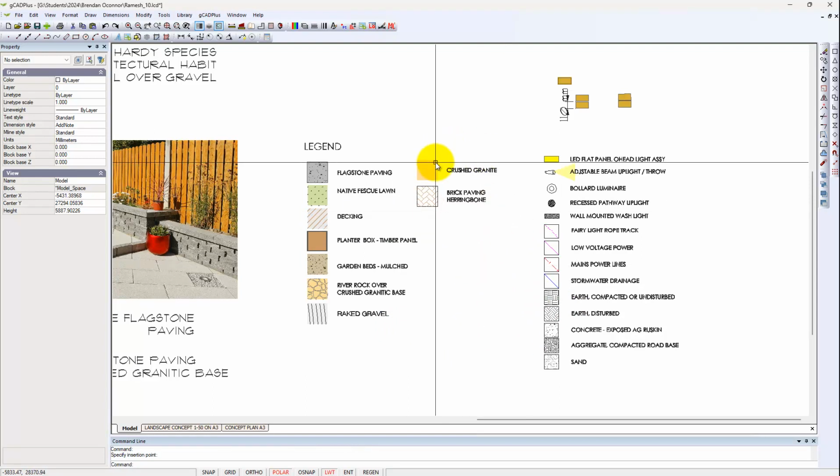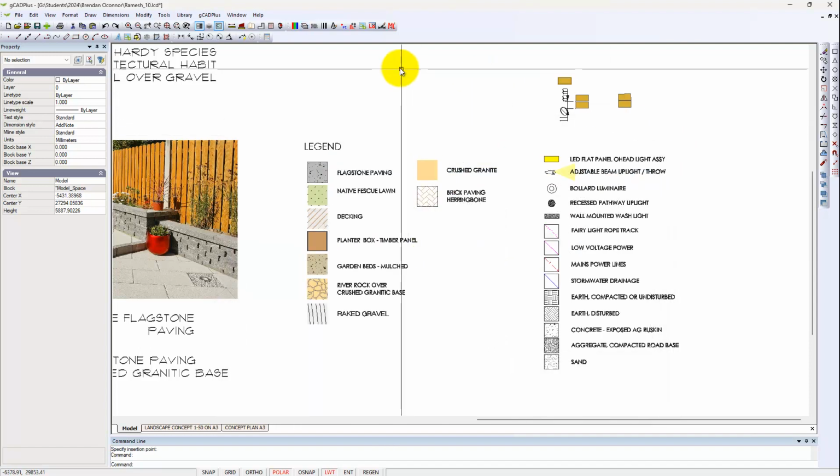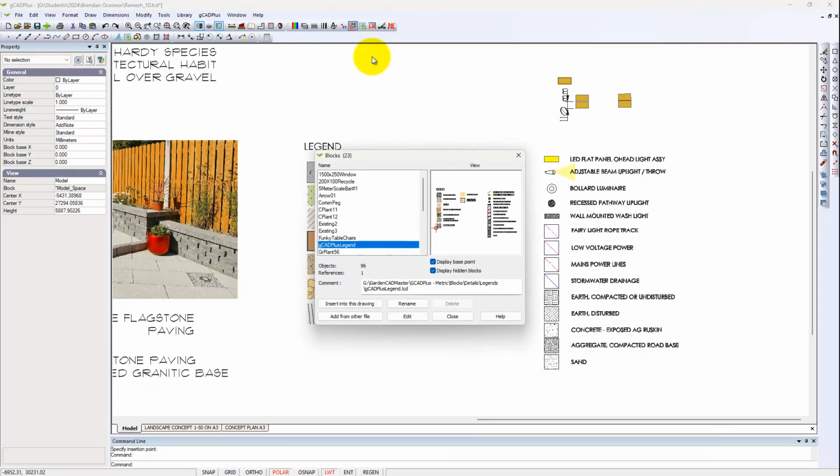And after quite a lot of detective work, I found that if we go to the Layers tab here, sorry, it's not Layers, although problems can exist in any drawing where characters that Windows won't allow are in there. But in this case, the problem was in the blocks library, and it's a flagstone. It's here, Newgrange flags. So it's a block that's been made by the designer.